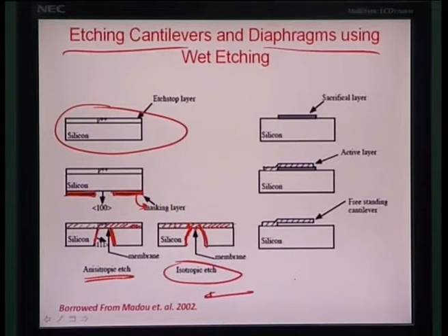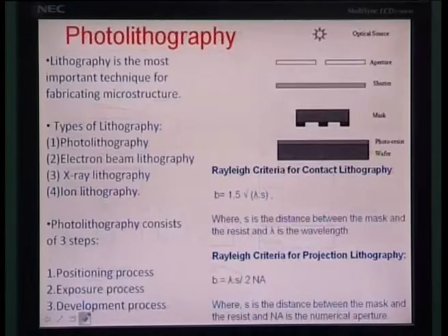If, on the other hand, you want to manufacture a cantilever, the best way is to put a sacrificial layer on top of silicon, as you are seeing here, and then cover it with a polysilicon or an active layer by some deposition mechanism. Removing the sacrificial material back, you are left with a freestanding membranous structure over silicon. You could alternatively use another mask to remove material from this end, so you have a perfectly separated cantilever structure for different diagnostic studies.